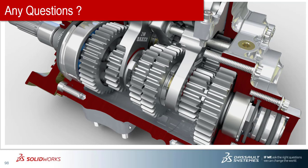Next question: can I use configurations in a large assembly? Yes, you can use configurations in a large assembly too, but you first have to decide whether your large assembly opens smoothly or not. If it lags or takes some time to perform well, please correct that assembly first and then use the configuration tool, because if you add one more configuration, it will again create performance and graphics troubles.